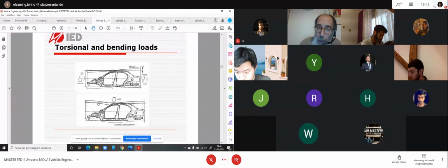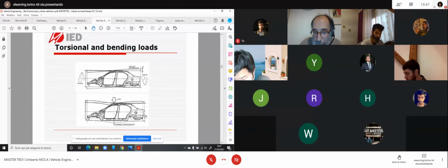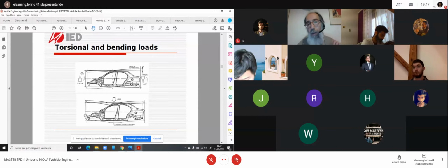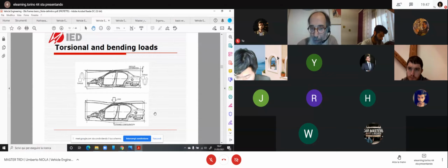Imagine sometimes you also can measure a deformation of the car even in the front overhang and rear overhang, simply because you have a flexible shelf or floor with the weight of the engine and other parts, and you have not enough rigidity on this part. So you can also measure a deformation in this part relative to the theoretical neutral middle axis of the design. Okay, is this all right to you till now?